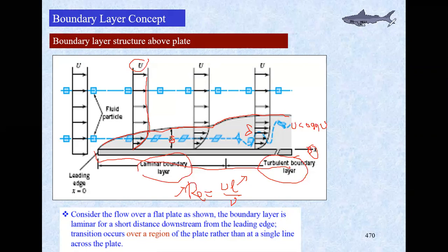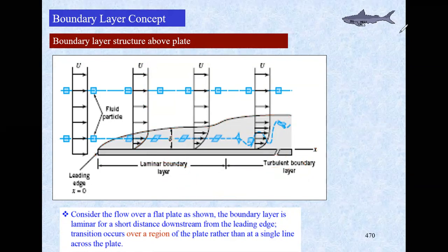How do we describe the flow over here? If we try to find the velocity distribution, remember that to find lift and drag, we need the shear stress and the pressure distribution, and the shear stress distribution can be obtained from the velocity distribution, du/dy. Yes, mu du/dy is the shear stress, tau_w over here.